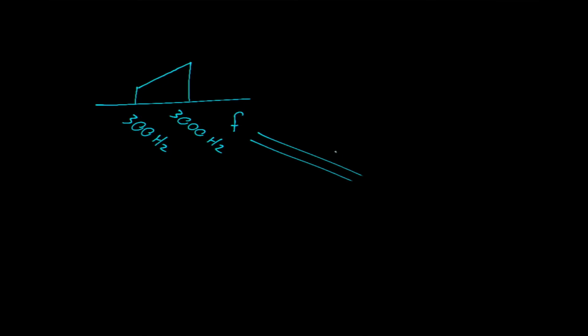Here's another way to look at this. Let's start with our voice frequencies. So in the frequency domain, I'm going to sketch this as a wedge. And we'll let that wedge of frequencies go from 300 hertz to 3000 hertz. And we said that voice frequencies do not transmit very well. Very difficult to do. However, if you run these frequencies through an amplitude modulation, so AM, you end up with something that's quite different.